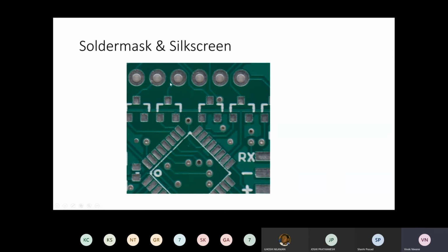Some of you, or hopefully all of you, have seen a PCB at some point. The solder mask here is that green layer of material. And if I look carefully at the board, what I can see, these things here are called pads. All right, whenever I have exposed copper like this, it has that silvery look. That's a pad, and that's something to which I can solder.